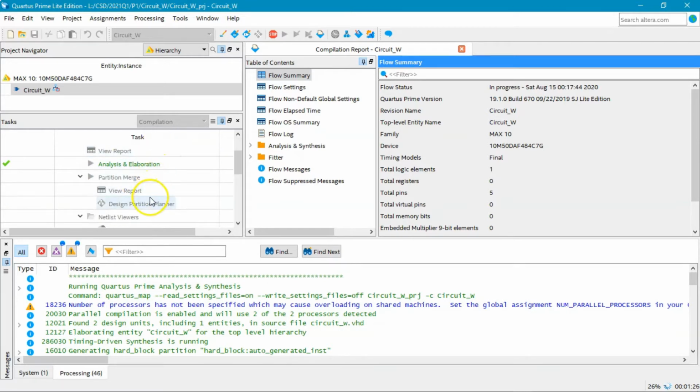So if we would like to see the schema, we can see that this schema appears here as the RTL viewer, right? Netlist is equivalent to schemas, and viewers is equivalent to a window where you see the schema. So you see RTL viewer and technology viewer, those are the ones that we have interest in, and in this project especially the RTL basically only.